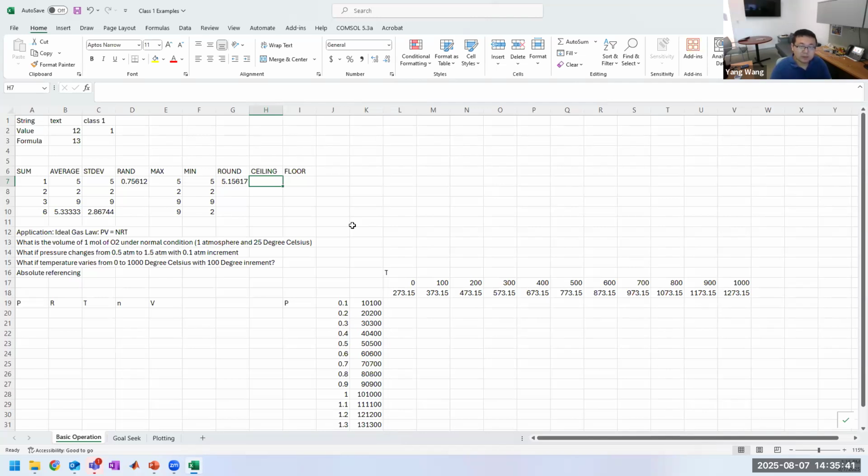So if you come up with an engineering design and find out that you have to make 5.2 sand filters, what do we do? Do we round it down, right, to 5? No, right? Because if it's 5, then it's not sufficient for you to do the job of removing the pollutant. Actually, we will round it up, right?